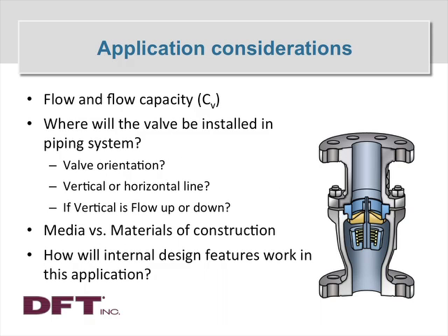Having given you a brief overview of four major styles of check valves, not all check valve designs work equally well in all applications, and you really do have a lot to consider. You've got to think about the flow and the flow capacity requirements. Where in the system is this valve going to be installed? What's the orientation of the valve?